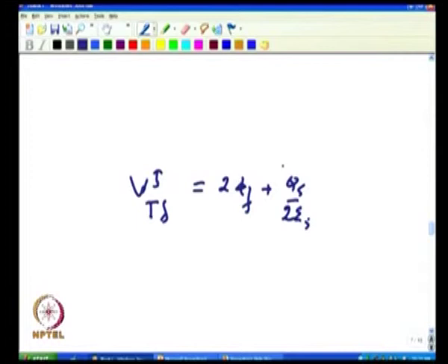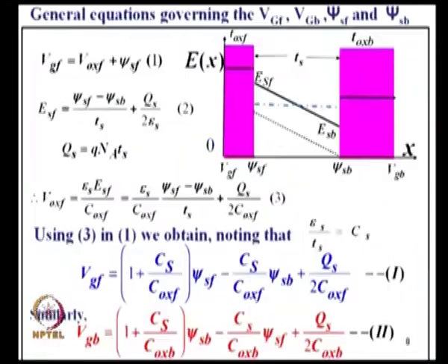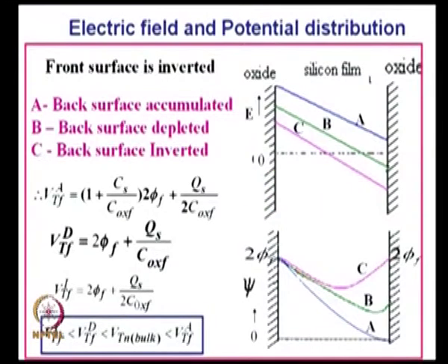So, this is a term which actually gives rise to the voltage drop across the oxide. In this case the drop across the oxide is small because the depletion layer charge is small. Now, if you reduce the doping, this can be reduced further. Ultimately, you can get the threshold voltage equal to twice phi f. Very small drop in the oxide before inversion, just when it is inverting.